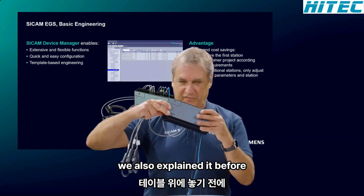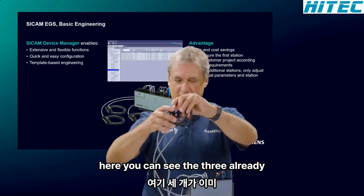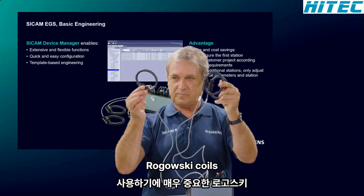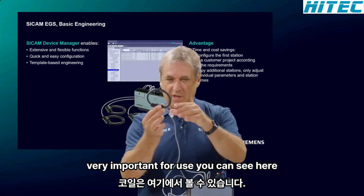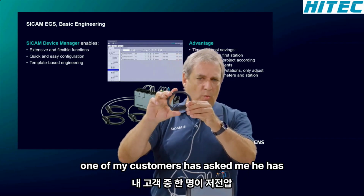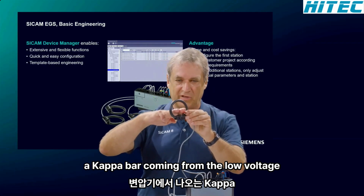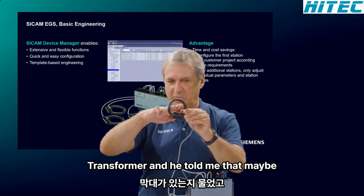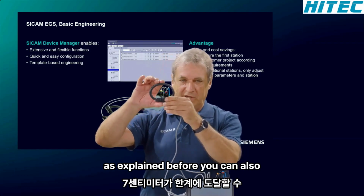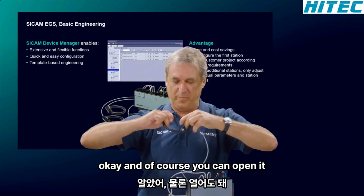We also explained it before. I put it now here on the table. Here you can see the 3 already attached Rogowski coils. Very important for you, you can see here the diameter is 7 centimeters. One of my customers has asked me, he has a copper bar coming from the low voltage transformer, and he told me that maybe 7 centimeters could be at the limit. As explained before, you can also slightly squeeze it. Okay, and of course, you can open it.